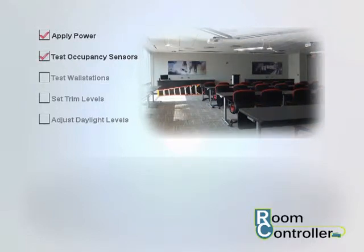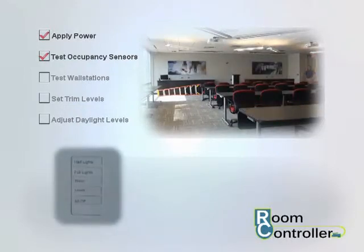Occupancy sensor testing is now complete. The sensors will automatically exit test mode after a period of 5 to 10 minutes. Test each button on your wall station to verify it operates as described in the installation documents and controls the correct lighting loads and dimmer functions.